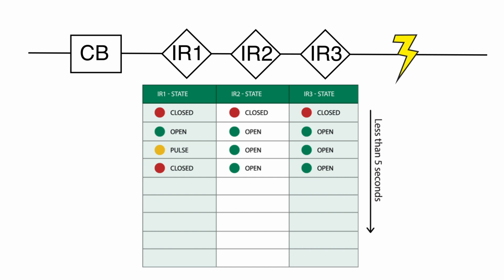When device number 1 closes, that brings voltage to device number 2, which will now use a pulse to test for a fault. Again, because there is no fault between devices 2 and 3, device 2 will close. Finally, device 3 will see a return of voltage and begin its PulseFinding technique sequence. Device 3 will see fault levels of current and continue through the configured test sequence. If the fault is persistent, device 3 will lock out. That is the basic operation of the PulseFinding fault location technique.